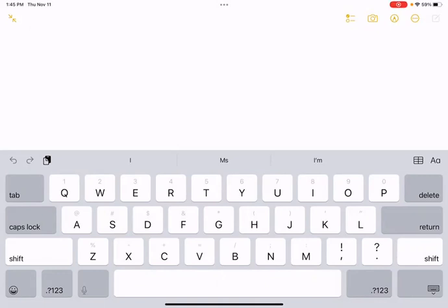So it's a piston cylinder where we have some gas, and we're going to assume it's air. And the first step is the gas gets compressed because the piston moves down and squeezes the air. So the pressure and the temperature both increase because of the ideal gas law.